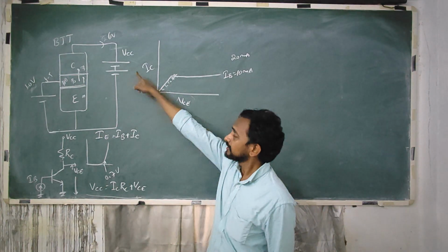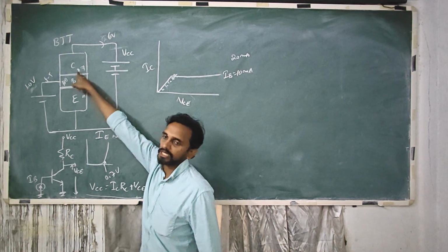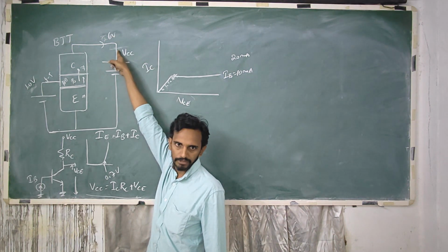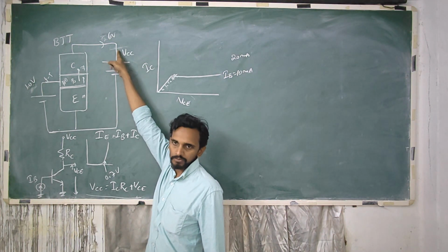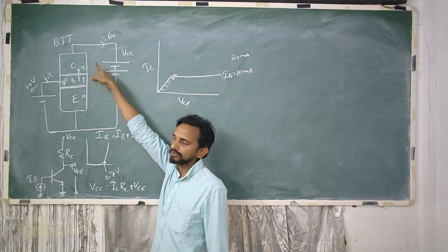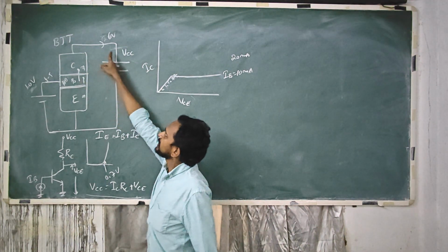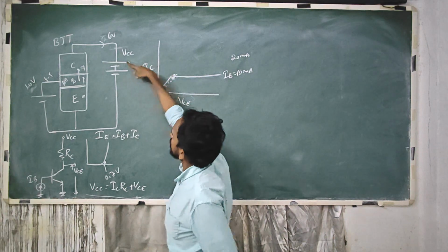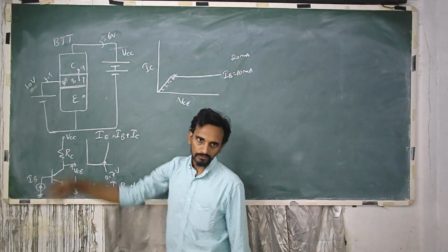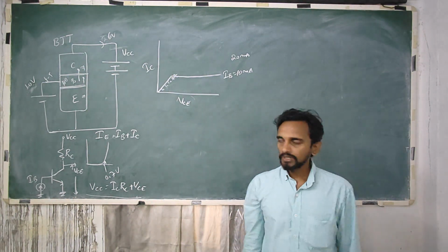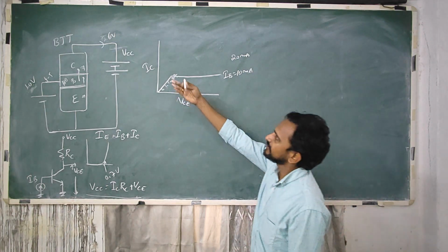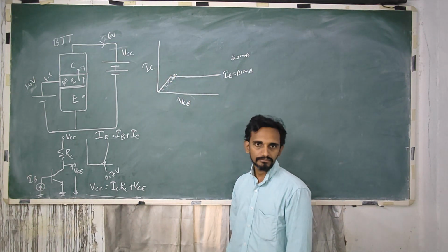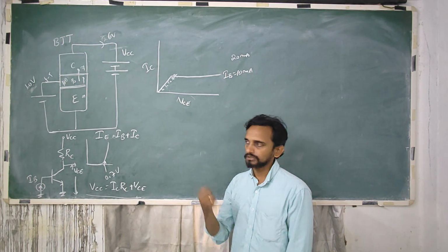So then this reverse bias condition will not be satisfied until I reach 10 plus voltage here. So up to 10 or 11 volts, no current will flow. After 11, once that VC value reaches a sufficiently high value, then the current starts flowing through it. Right? So from 10 and 11 I need to go up to, let's say, 15 volts to capture all the electrons.